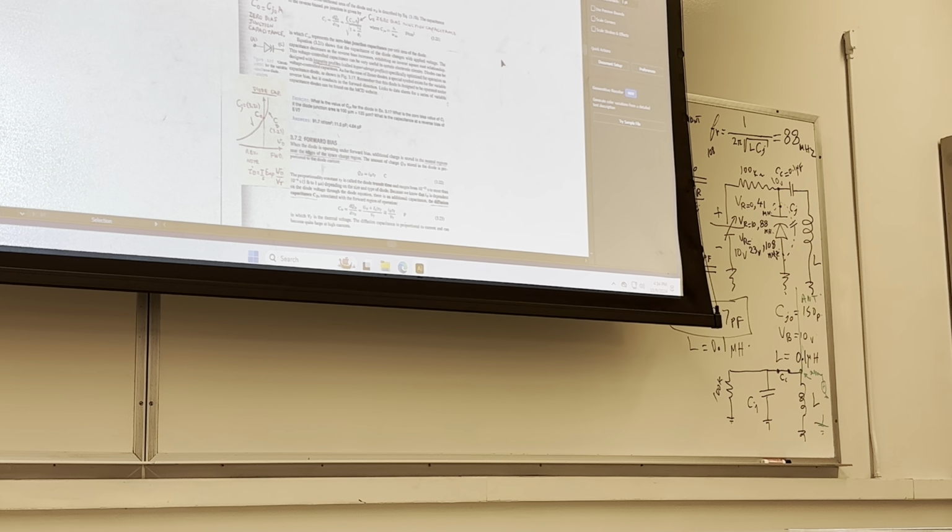So when it gets the power, electromagnetic waves, it excites and generates a current into the LC circuit. And the LC circuit starts to resonate exactly at the incoming frequency, which is the radio station you dialed. And that frequency goes for amplification. It goes in, amplified a few times until it's a substantial signal.